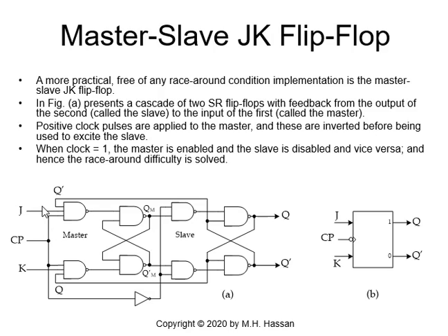So we have J and K, and one will act as a master and the second one will act as a slave. The output from the master is QM here and QM prime, and this is a clock circuit. So we have the clock pulse goes to a 3-input NAND gate on the top and the bottom, and the clock pulse is inverted for the slave. See, we have an inverter, so the slave will have an inverted clock pulse.